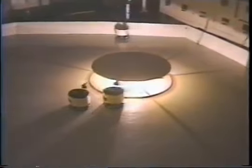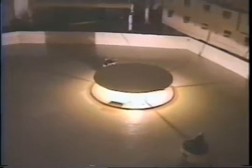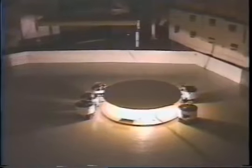In this demonstration, a round box was first moved from the center of the room to the goal at the right of the screen. The task is divided into 3 steps, with a reactive controller designed for each step. Transitions between steps are specified as locally sensed perceptual cues, a simple concatenation of binary sensor values.